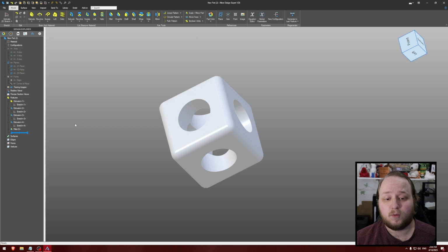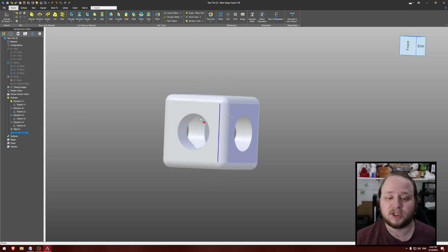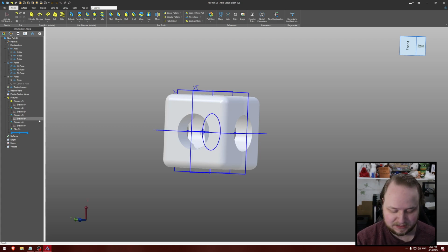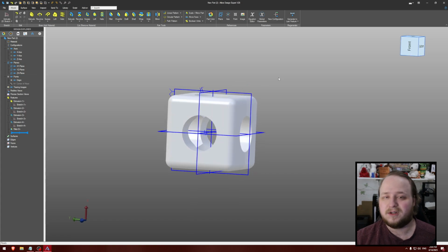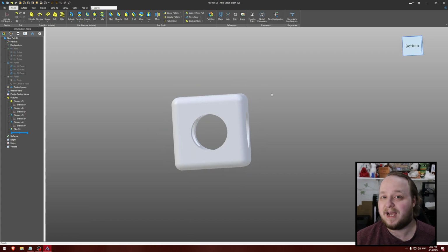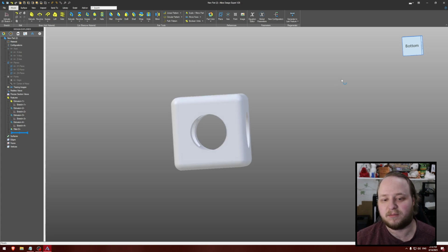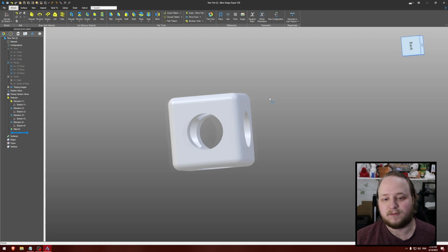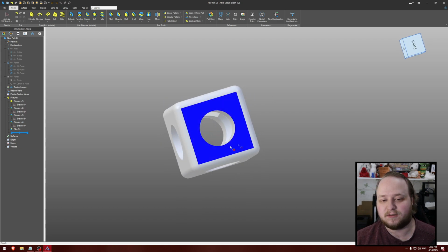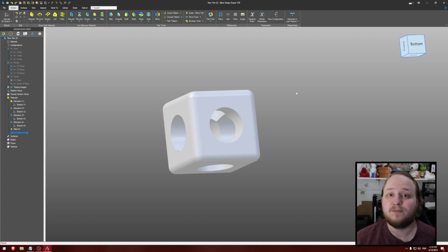So remember when I asked you guys to do the other 2 circular holes through our shape? Did you remember to do them mid-plane? As in, did you remember to select one of the planes that is centered to the cube? Or did you figure something else out? Did you figure out by accident maybe that you could do a sketch on one of the faces of the cube? In fact, you can, and that makes CAD really powerful because any additional face you create can be used just like a plane. But there's one last thing that's even more amazing.